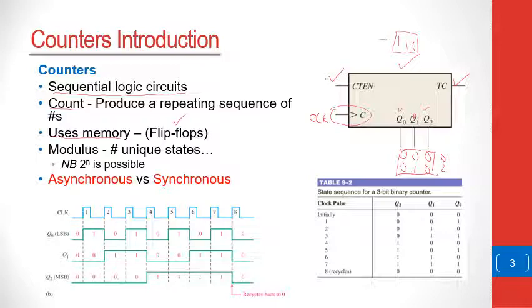So in actual fact, if you have a 3-bit counter, it means the counter can move from 000 to a maximum of 111. That is, it can move from 0 to a maximum of 7, which means the counter itself will have 8 unique states, or 8 unique output sequences, so to speak.